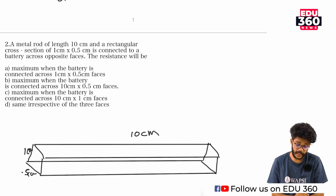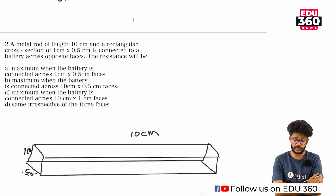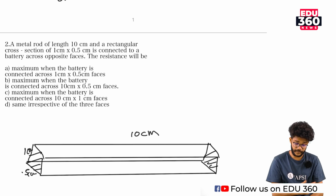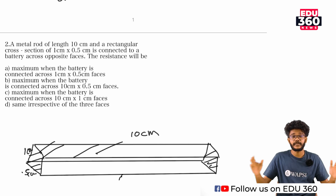When will the resistance be maximum? Option A is maximum when the battery is connected across the 1 centimeter into 0.5 centimeter faces. That means they are connected across these two faces. Option B is maximum when the battery is connected across 10 into 0.5, which is here and this. We can see that the resistance increases when the length between the connections increases.